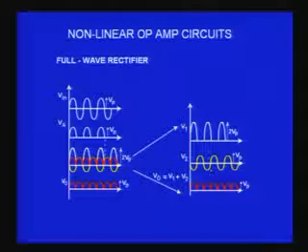So these two signals will be added at the output, and what I get will be the sum of these two. If I add these two, what is going to happen? This is 2 V peak, this is V peak in the opposite direction. So when I combine these two, I will get only 1 V peak in the upward direction.